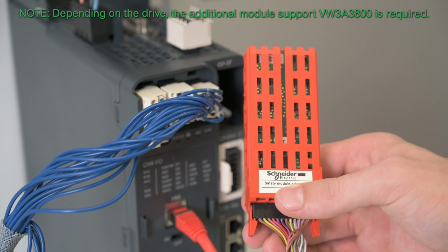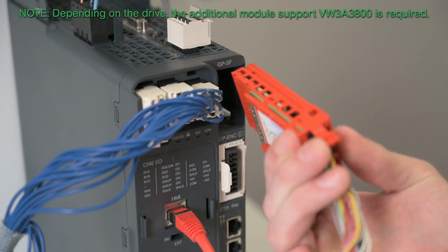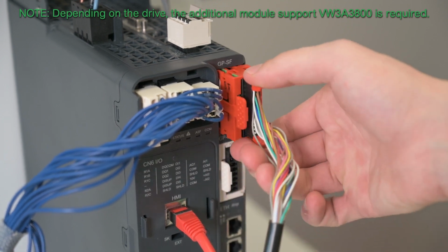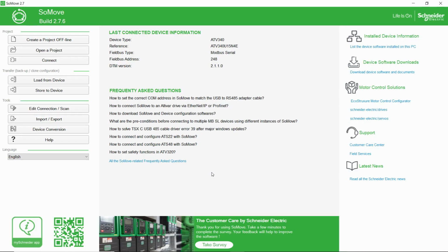After the installation of the safety module inside the drive, but also the installation of the other required options, such as the encoder module, connect with SoMove to the drive. Once connected to the drive, verify the topology of the drive.